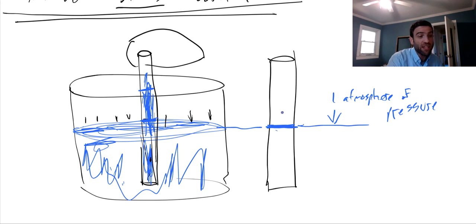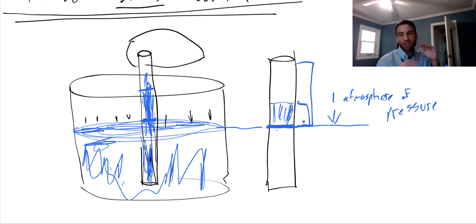So now I take away the air in the straw, so now there's no longer any pressure from that, and the water starts to rise, and it will keep rising until the pressure of the column of water inside the straw above this free surface is able to replace the entire pressure that used to be supplied by molecules of the atmosphere, right? So that's what's going on when we drink from a straw.